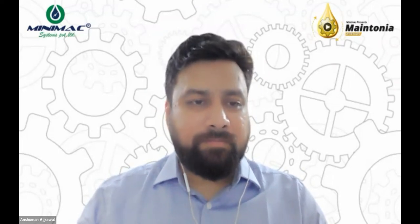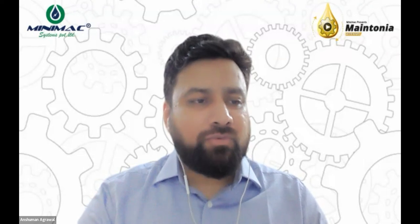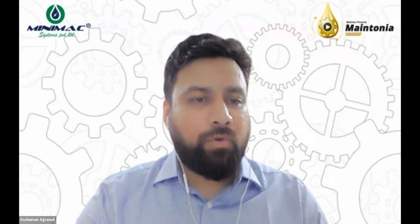Right. Okay. The next question is how to reduce the bubble formation in oil tank. So some methodologies of reduction in bubble formation can be used, like the return line. All the return lines should not be hanging on the top of the tank. They need to dip down within the level of oil.